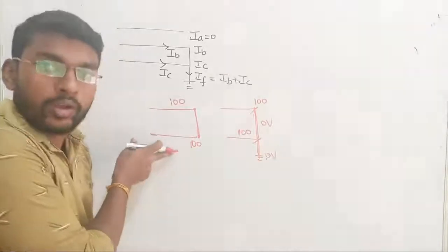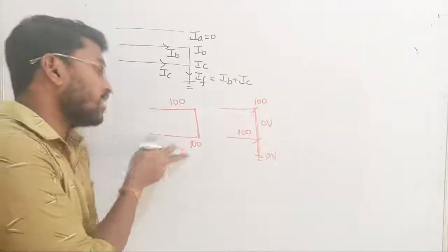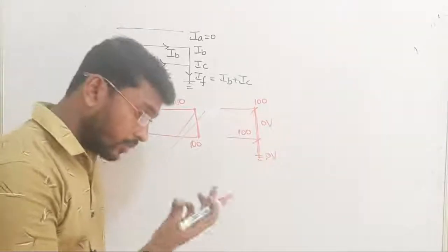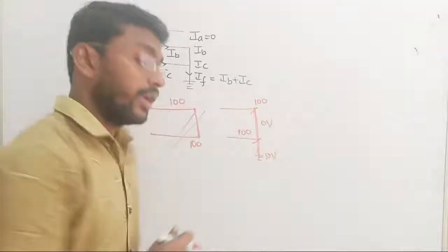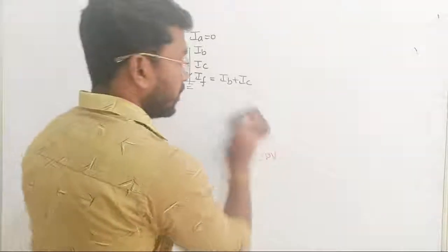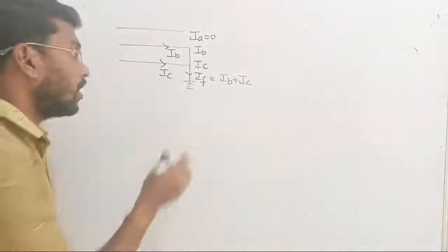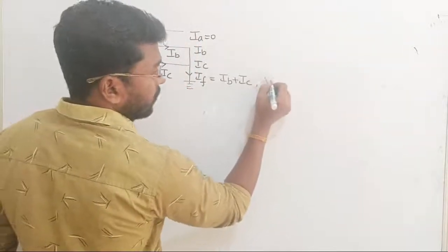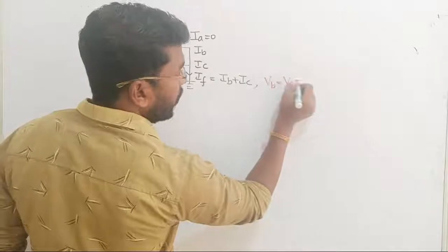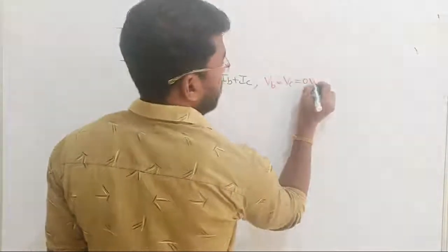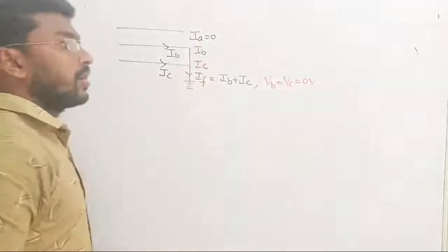See there, in the other concept, can you inject? No, there is no point of grounding. Grounding means the ground reference point should be required, right? So in a double line to ground fault, the beauty is what we are going to suggest: because of the short circuit with the ground, the phase B and phase C voltages are going to be 0. Why is it 0? We know the reason, right? Yes, it is going to be 0. Already we know something. Let us proceed further.